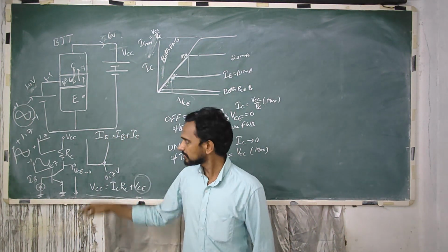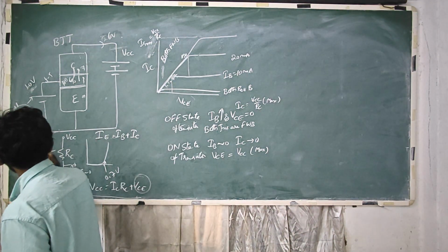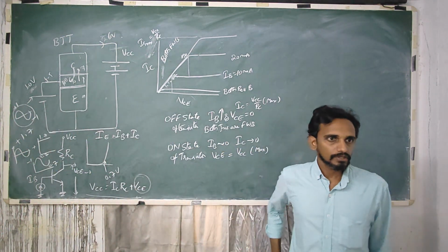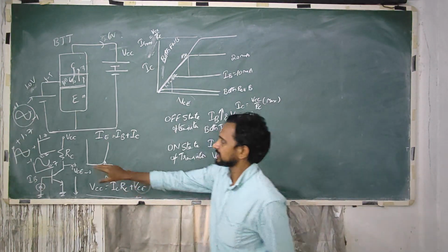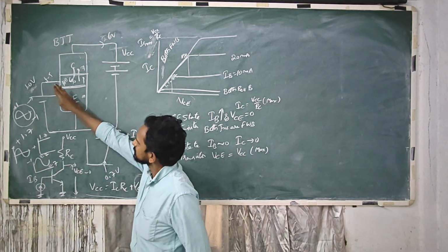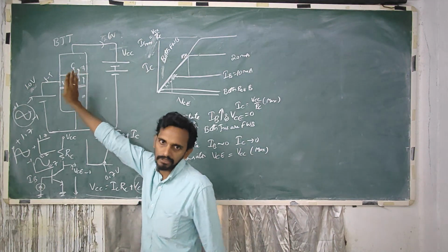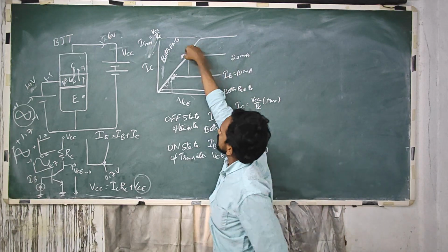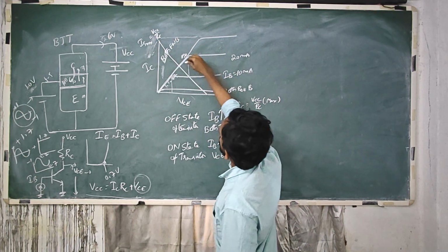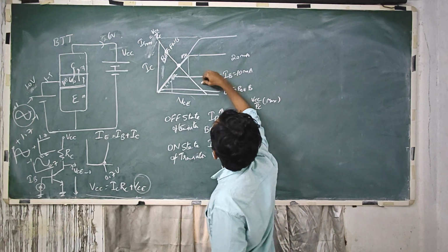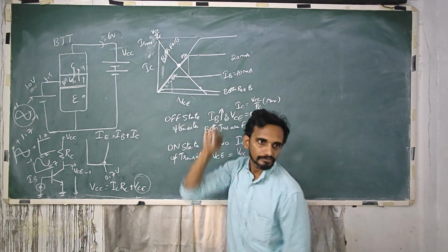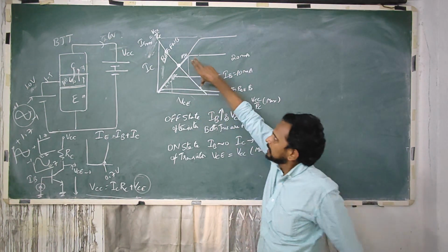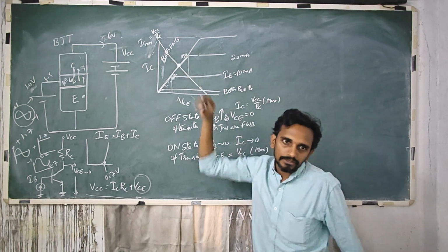This is now 0.7 and this is 2.7. Once I push this entire signal into the positive quadrant, the transistor will operate in amplifier condition. So I have to ensure my transistor operation is in between these two. This is the operating region of the transistor.